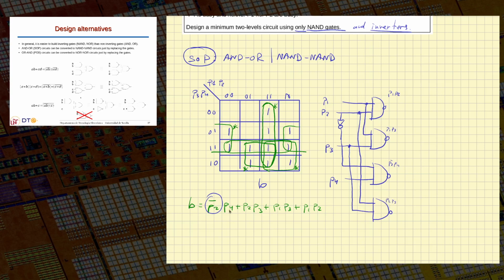And all that I sum with another NAND gate. So as you see, I'm not changing my expression, just using gates as if they were the original AND and OR. And that will obtain the solution for my circuit.